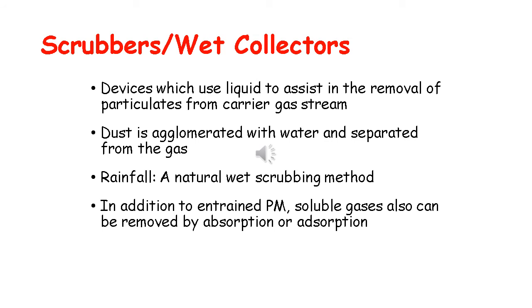Scrubbers are devices that remove particulate matter by contacting the dirty gas stream with liquid drops. Generally, water is used as the scrubbing fluid. In a wet collector, the dust is agglomerated or collected with water and then separated from the gas together with the water.